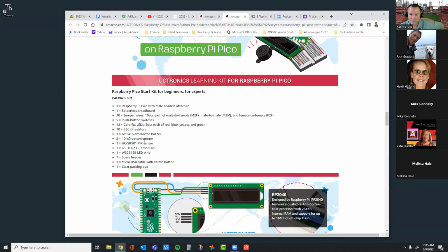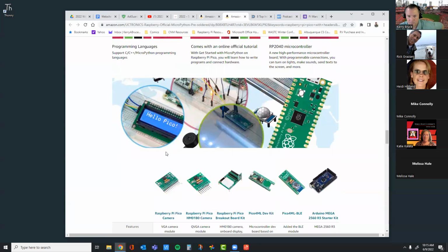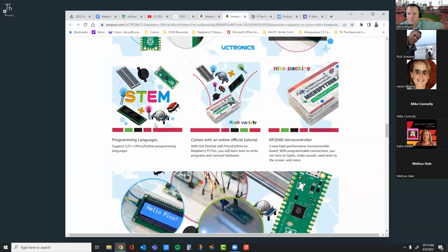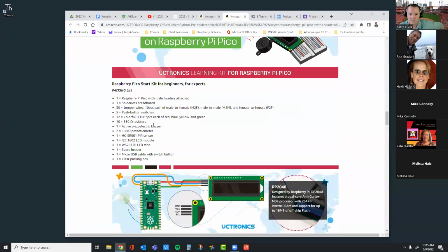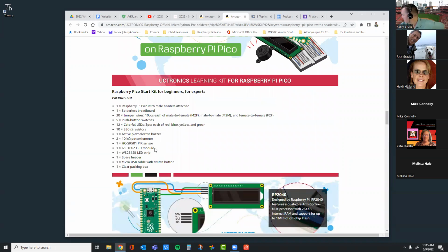There's a PIR sensor. And then the LCD module, the module that they have here is a 4-pin module. I think there's a picture of it later up above, but I had to go search to find one that was 4 pins. I have some that have like 20 pins, and one that has 3 pins, and I was like, oh crud, I'm not going to be able to do this. But then I found one. So the 1602 LCD module has the 4 pins with ground, VCC, SDA, and SCL.